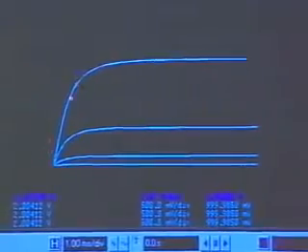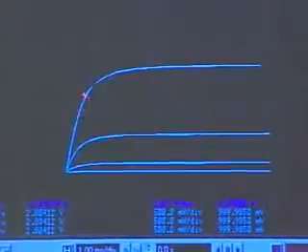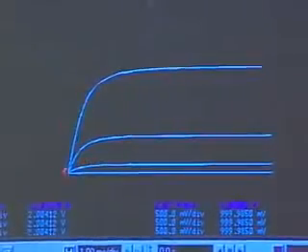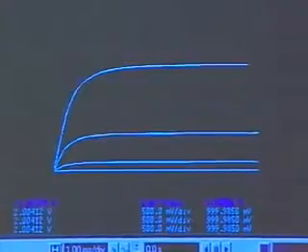So in the beginning, I hid the right-hand side behavior from you and showed you just the resistive behavior out here. When I increase VDS to be much larger, the curve saturated and I got the saturation region operation of the MOSFET. And notice, as I increase my value of VGS, the saturation current also increases according to a square law behavior.